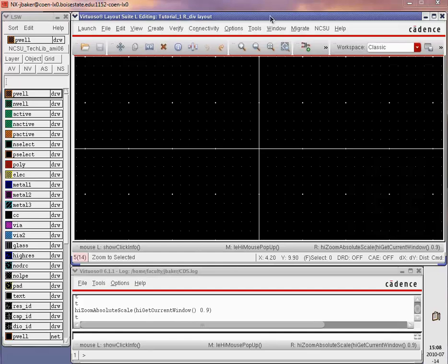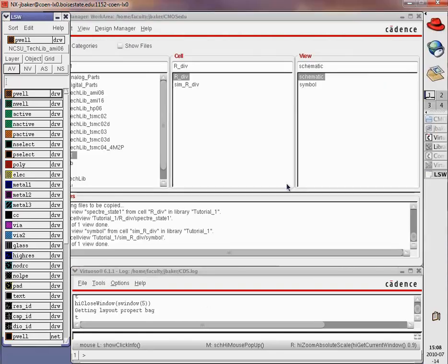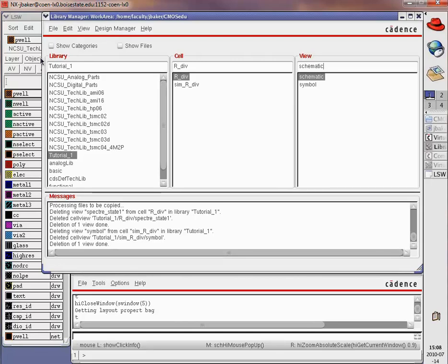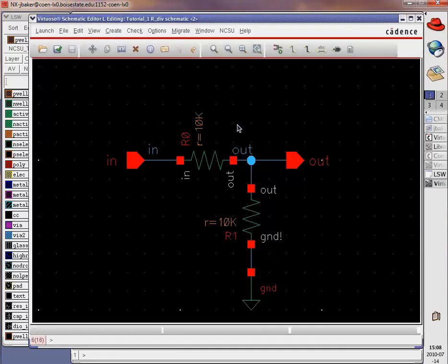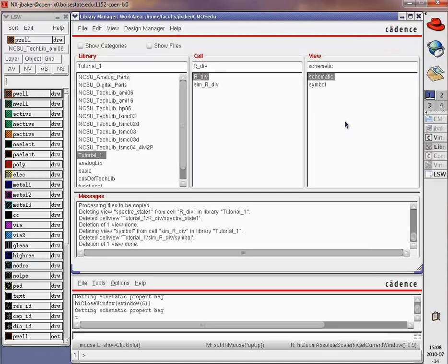And so let's close this cell for now and go up to the library manager, and we need to make a resistor. It's because in this cell here we had a resistor from the symbol, but we don't have layouts. We don't have a layout that we can place in the corresponding layout here. Let's see, view, refresh. Okay, so what I'm going to do, I thought I made a layout cell here. Anyway, let's go back, and maybe it didn't save it because there was nothing in it.